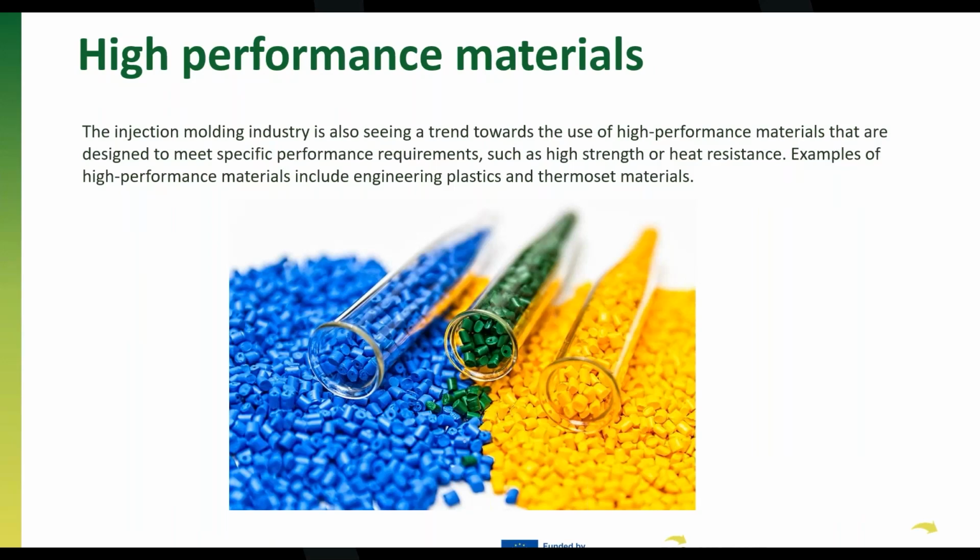high performance materials is not only about weight, but also about the materials themselves. In the case of the bio-based material, this is also really interesting, how we can reinforce these different materials in order to obtain the mechanical properties that we want, and how this reinforcement will affect the injection molding process. We have to keep in mind that, for example, if we are going to use fibers to reinforce the material, these fibers will not be melted during the injection phase. So we need to fully understand the behavior of the fiber and the interface between fiber and plastic, in order to predict these final properties.